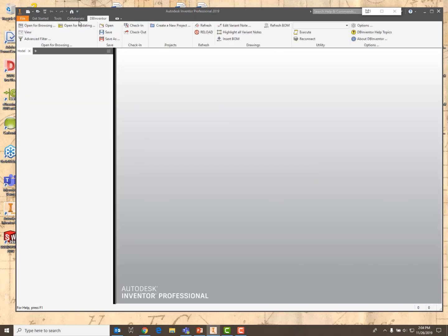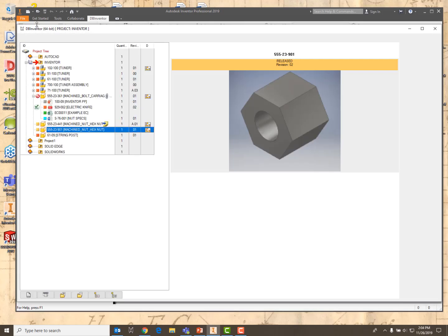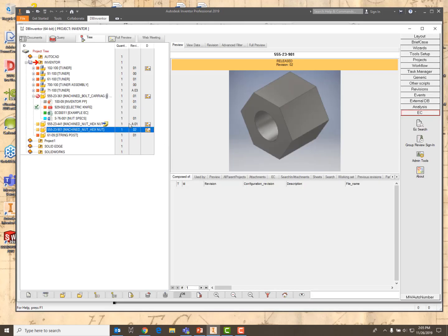So now we can go back to the MechWorks browser, and you can see that it's revision 02. If we go to the previous revision tab over here, here we can see the previous revisions done to that document. Then obviously this is going to remember all those previous revisions for you, zip them up, save them up. And the reason it would do this is there could be a reason for you to go back to a previous revision. In fact, let's do that.